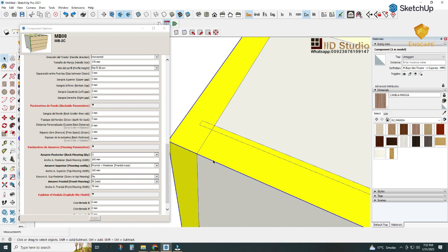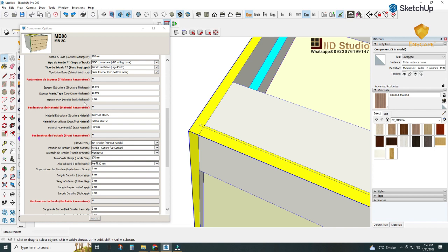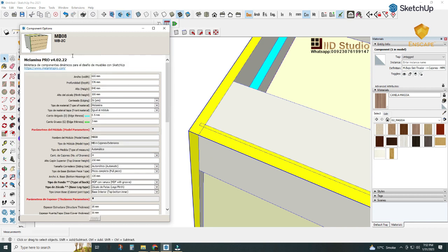And also you can change the back thickness. Back thickness, if you have a solid back, not this type of back. This back thickness is already there, you can adjust this size of 3 mm or 4 mm. Let's check it, 5 mm. You can change it here. See, now it's 5 mm. Turn it back.